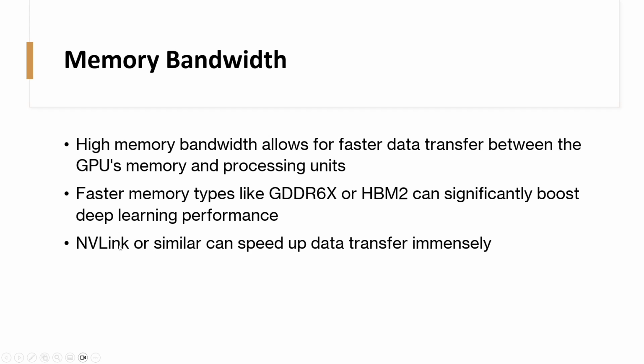Another thing to keep in mind is that NVLink is offered for a significant amount of GPUs. NVLink is actually linking two GPUs directly together so that they can almost be used as a single GPU and kind of share RAM and transfer directly between them at super high speeds. I think NVLink 4 is like a couple hundred gigs per second. So, really, really fast, and it makes a huge difference if you're training big models.